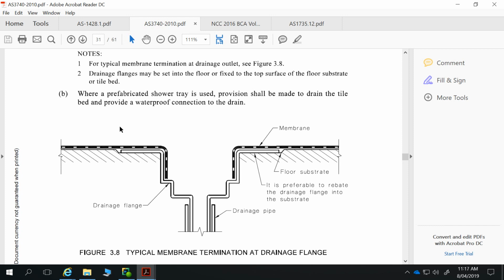So this drainage flange here is actually set down into our concrete floor. So at the point of pour, you'll produce slight accommodation in the top of your concrete there, and space for that drainage flange to go in there. But that's the top of our concrete, and then we have our screed above that. So this top here is set down 50mm from our finished floor level for the rest of the building.